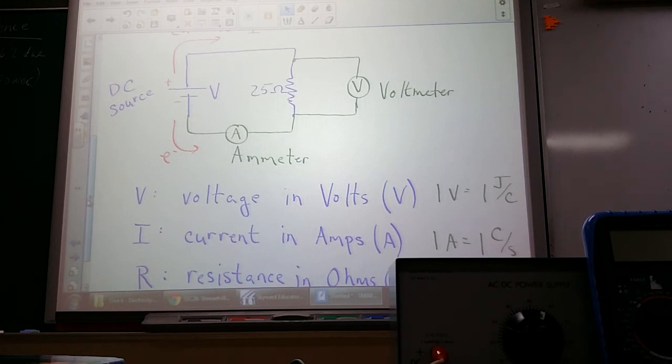I suggest the gold ones are nice. There's a variety of them. The gray ones are okay, but don't pick the ones on the upper side that say 1 ohm. That's going to heat up really fast and put these under too much stress. So stay away from 1 ohm, but you can certainly choose the rest. If you want a different variety, the little ones in here are good too. Don't go too high, probably no more than 200 or 300 ohms in that first one, and just make sure they get back into their correctly color-coded bins when you're done. But these are also okay.